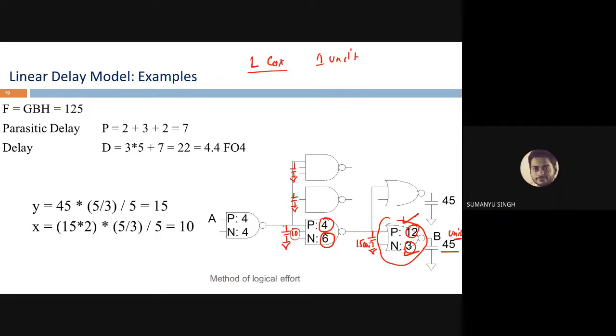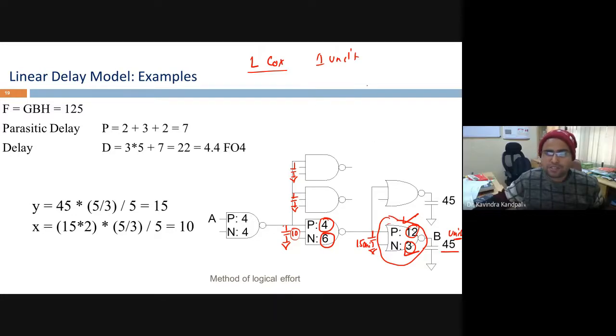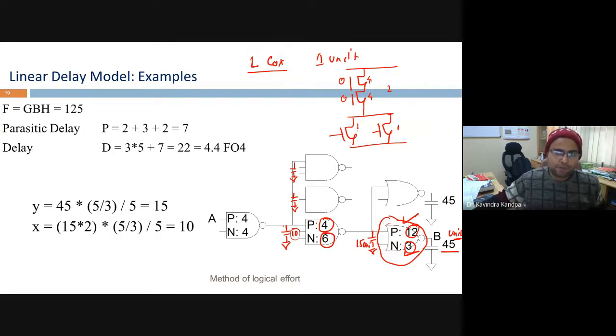Yes, sir. So for this, first you just make the schematic of this particular circuit. If you make the schematic, you know that there are 2 PMOSes which happen to be in series, and there are 2 NMOSes which happen to be in parallel. You know that if this is supposed to be of the net equivalent 1, and here it is supposed to be 2. So you need to put 4 here, 4 here, 1 here, 1 here, right? Let us suppose I'm multiplying, because sizing doesn't mean you need to maintain the absolute values. You need to maintain this ratio. If I say this is X, this should be 4X, this should be 4X.